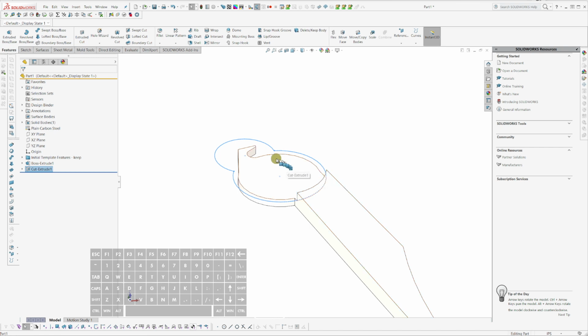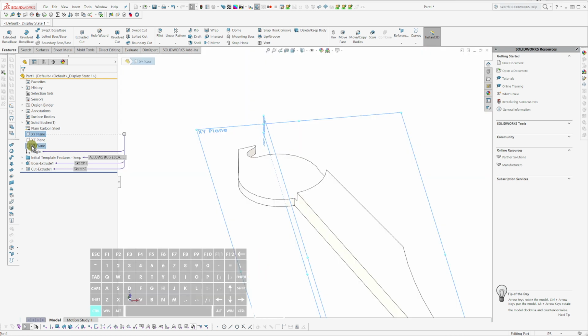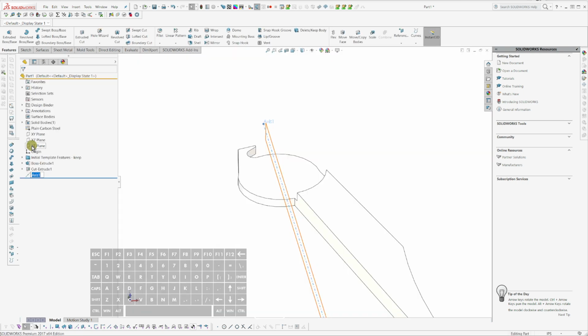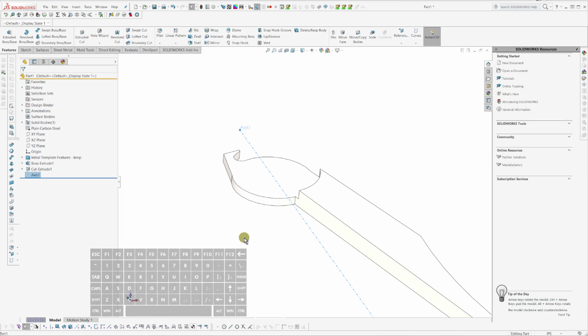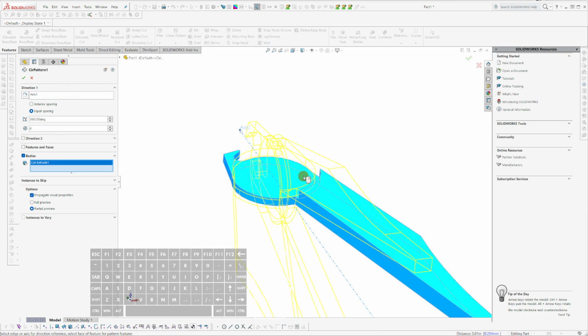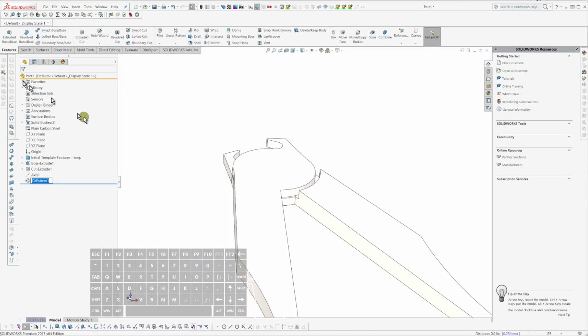And I am going to go ahead and I'm going to create an axis here to revolve around. So I select the 2 planes, Control / on the numpad is my axis, create axis. It's my shortcut. Let me know if you want my shortcuts. I have custom shortcuts that work very efficiently for me. And so now I have this axis, and then I'm going to do a revolve circular pattern. That axis predefined. Body's this guy, not 4, 2. Okay.